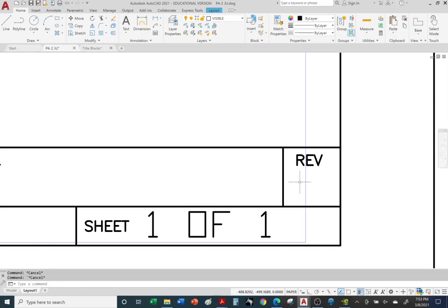Typically, you'll start with the new revision, and some companies like to use a little dash like a minus sign, or NC, no change, meaning it's the original, right? The original one. Instead of using OG, they use NC, no change. Okay, and some companies will start with the letter A. You go in alphabetical order, so this can be revision A.